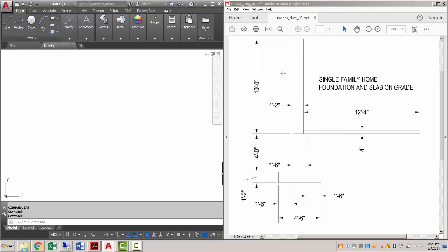And you can see some of these different types here. For a particular dimension, these are the extension lines, and they come off of whatever you are measuring. So here we're measuring the exterior wall from the base to the top, and you can see the extensions are offset by some amount to show a little bit of a gap, so you can tell the difference between your features and your dimension lines. So these are the extensions. This would be then the dimension line, and these are your actual dimensions.